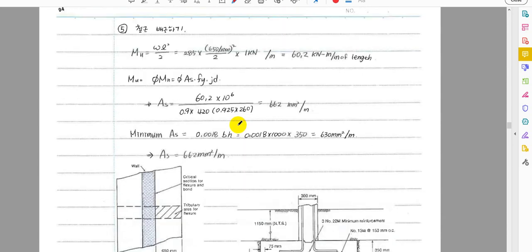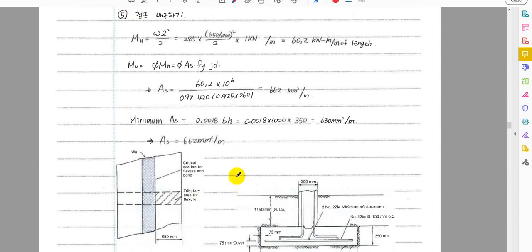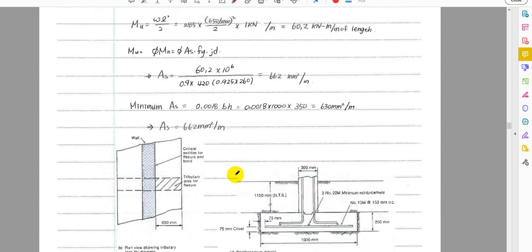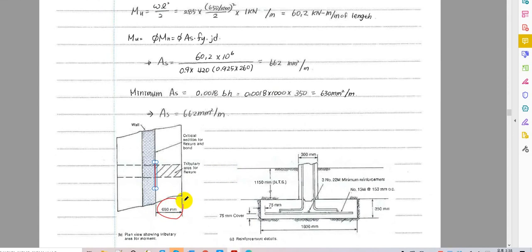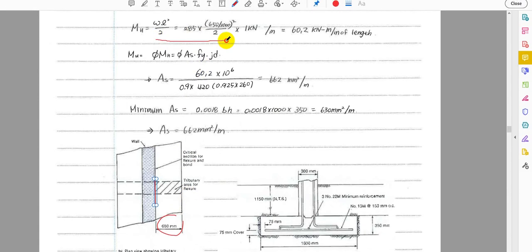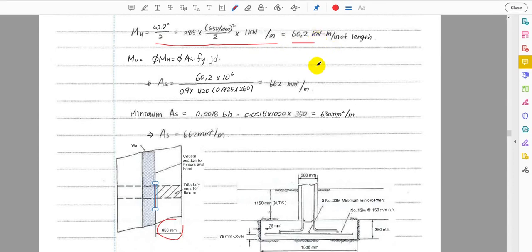And we go and calculate the flexural design, which is based on moments that act on the foundation. When you calculate moment, we have to consider from the face of the column, as I said, from the two-way design case, and we get this length for the span of calculation of flexural moments. We use this formula to calculate a flexural moment, which is 60.2 kilonewton meter per meter.